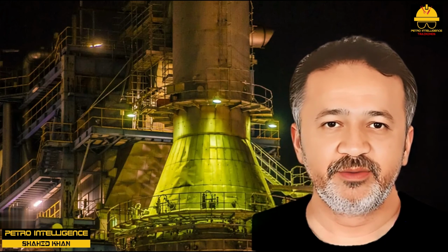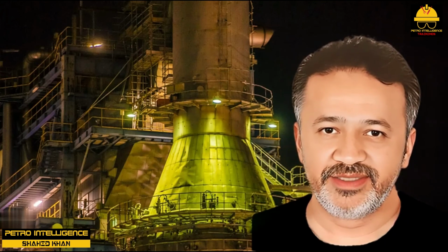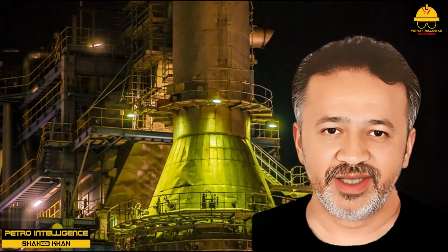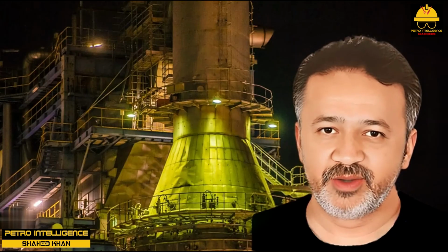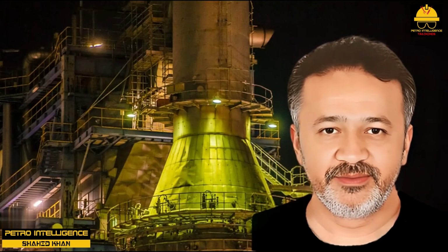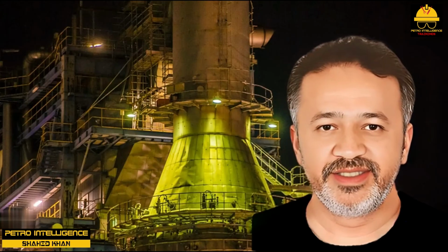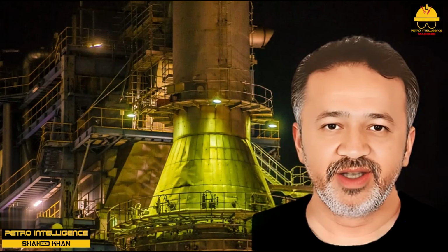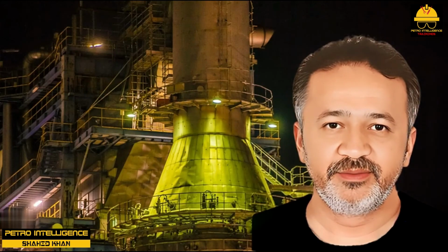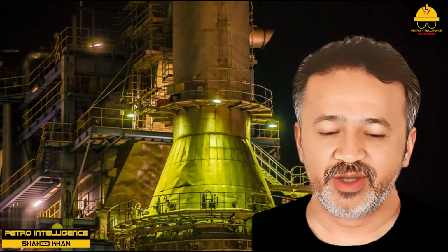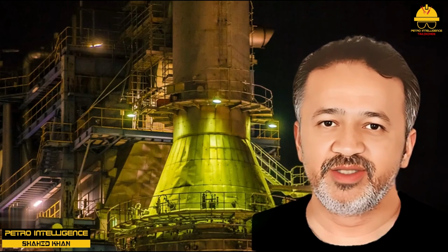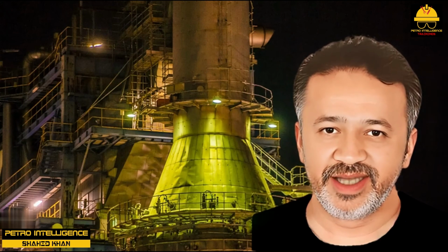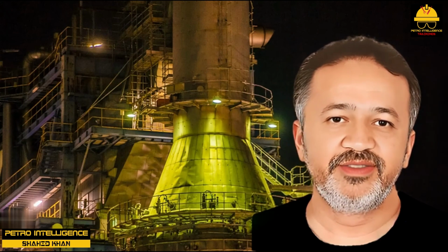Please also note that fired equipment either without burner pilot lights or with extinguished burner pilot lights have been known to explode during operation, as the pilots, when lit, do provide some means of safely relighting or keeping main burners alight. An explosive mixture in the firebox is indicated for methane, that is, natural gas, when the methane content is between 5% and 15%. When the firebox methane content is below 5%, the air-fuel mixture is too lean to combust. When the methane content is above 15%, the mixture is too rich to combust.